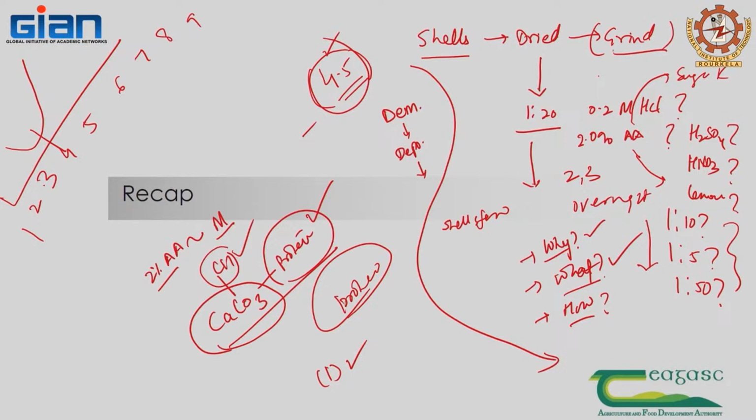So if you add acid without removing the residue, then you are again mixing everything together. So what will happen after adding alkali, you will centrifuge it, the alkaline solution you will adjust to a pH of 4.5, and once pH is adjusted, you decant the top solution which will still be containing some of the free amino acid, some of the nutrients, acidified water. That water is a waste water, whereas it can be used easily for production of duckweed, macroalgae or microalgae. That's the only way you will be able to introduce circularity.